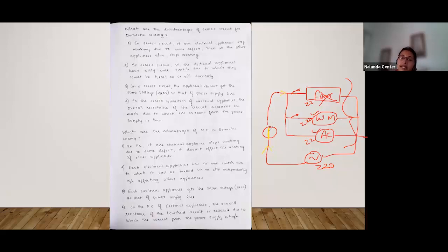Now, when tremendous current passes through, this copper wire has comparatively higher resistance. So this is going to create more heat. When more heat is created and it reaches a melting point, this particular wire is going to melt. And then this melts and breaks the circuit, and the entire current flow is disrupted. Thus, all the equipments are saved.